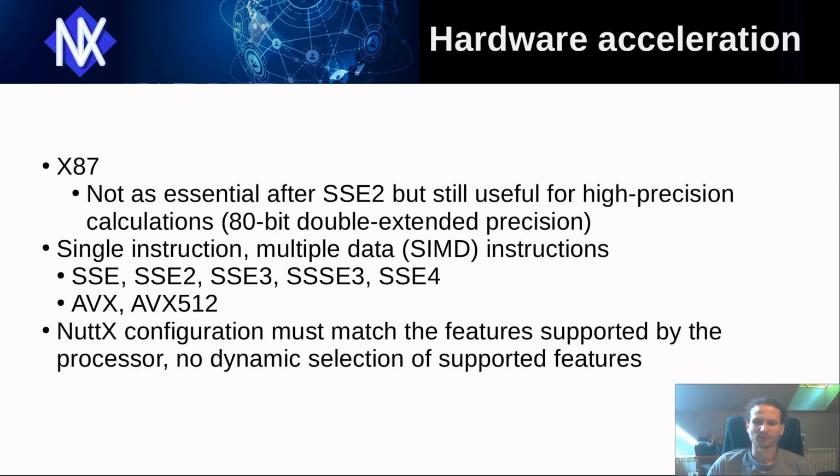Support for a given instruction set must be enabled from the NuttX configuration level, and the NuttX configuration must match the features supported by the processor. There is no dynamic selection of supported CPU features. So if we enable a specific instruction set in the configuration but it's not supported by the hardware, NuttX crashes at the early boot step. Unfortunately, at this boot stage, the serial port is not available, so we don't get any valuable error message.